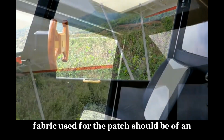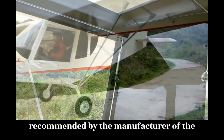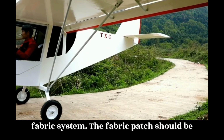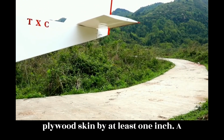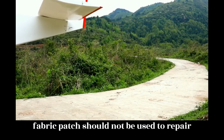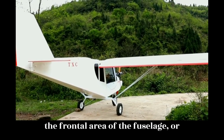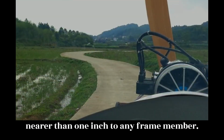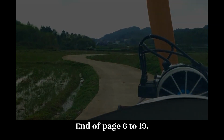The fabric used for the patch should be of an approved material using the cement recommended by the manufacturer of the fabric system. The fabric patch should be cut with pinking shears and overlap the plywood skin by at least 1 inch. A fabric patch should not be used to repair holes in the leading edge of a wing, in the frontal area of the fuselage, or nearer than 1 inch to any frame member. End of page 6-19.